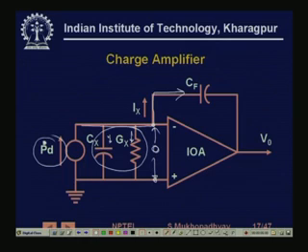This is the low impedance path, and therefore the current will flow into this capacitor and will get integrated. Since the input is pressure dot, the output voltage is going to be proportional to pressure. This is highly used in piezoelectric crystals, because even if these resistances vary, it's not going to affect the result. You can connect a cable and the cable capacitance does not affect the sensitivity of the device, as we have seen in the case of piezoelectric.